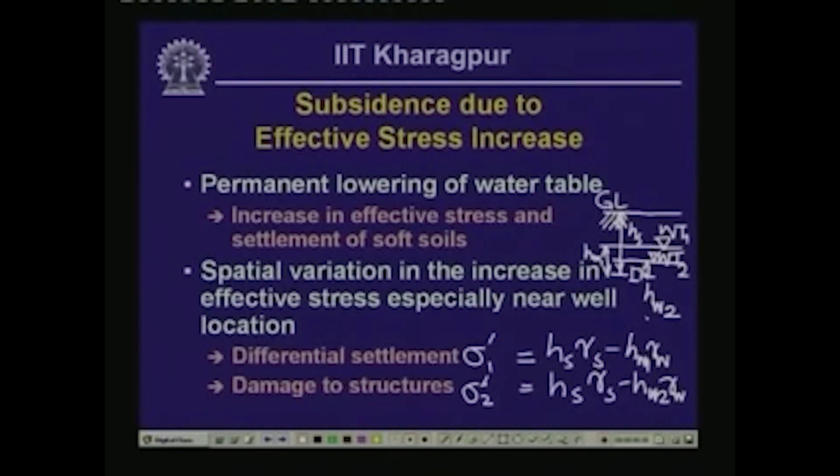Now you should also recall, since lowering of water table more often than not takes place under the influence of dewatering from water wells, the lowering of water table is not going to be uniform spatially, and it is going to be more remarkable near the location of the water well than at a greater distance from the water well.